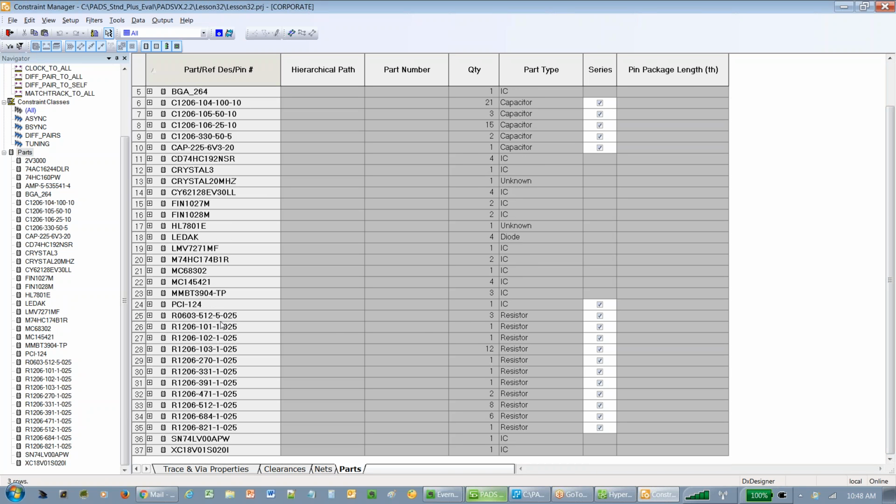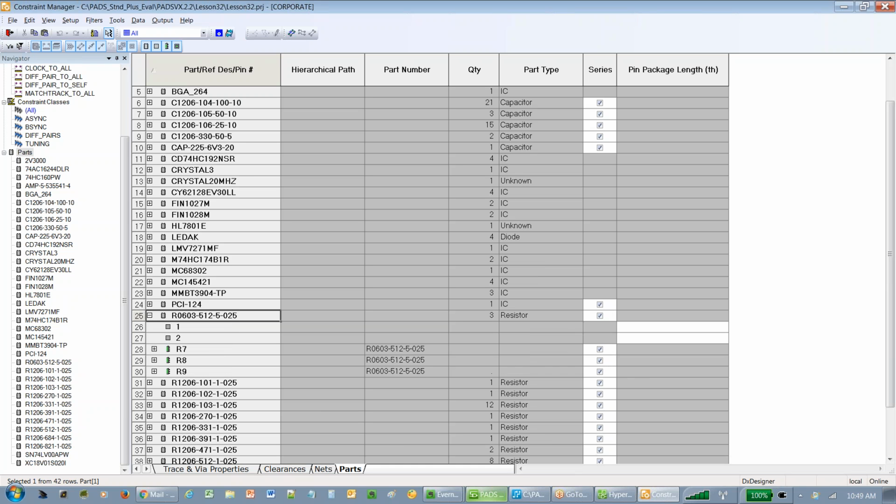Our tool has the ability to pick up passive components and create what's called an electrical net. So instead of you having to worry about doing length matching for, say, termination resistor series terminators, I don't have to worry about length matching on one half of the net and one half of the other net. The tool can auto create what's called an electrical net, whether or not the tool sees a particular component as an electrical net, and you can do it by reference designator as well.